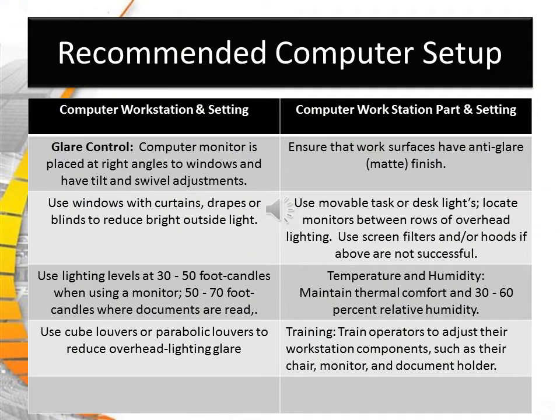Glare control. The computer monitor is placed at right angles to windows and has tilt and swivel adjustments. Use lighting levels at 30 to 50 foot-candles when using the monitor, and 50 to 70 foot-candles when documents are read.